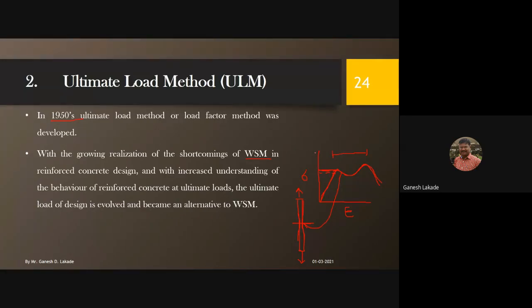If you plot the stress versus strain graph for concrete also, then for plain cement concrete, where we cast a beam and apply a point load on that concrete, you found that as you increase the loads, some minor elongation takes place, and that relationship is linear. But after some time, deformation goes on increasing, but the load is not carried by that concrete, and sudden rupture will take place. So this is the general stress-strain relationship for concrete.